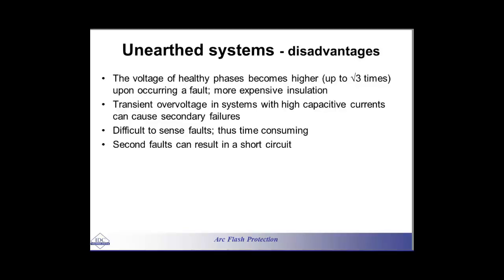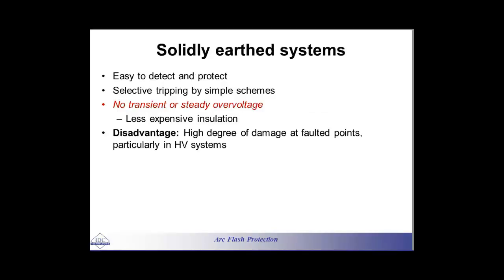However, if there is a fault, in that case you're going to get into trouble, because that fault is not going to be detected because you have not provided for it. I'm talking about earth fault. That earth fault will not be detected because you have not created any earthing system, right? And if it stays in the system, that can cause a problem like insulation problem in the long term, right? Also, if a second fault occurs, in that case there will be a connection between the two faults, and you do not have any protection system, and your system is blown, right? So therefore, it is much to your benefit that if you have something like a neutral point available to you, you just make it solidly earthed, okay?